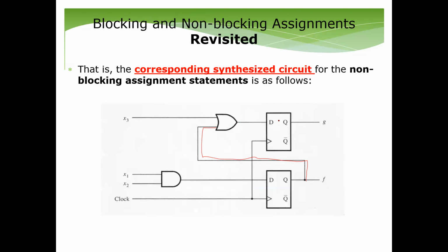Right, so if I give you a code and I ask you to draw the circuit that Verilog will synthesize to, you have to clearly and carefully read the code to make sure whether we are using blocking assignment or non-blocking assignment, because the resulting circuit is not going to be the same.